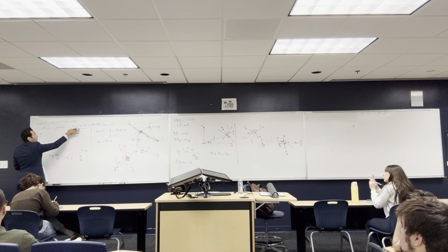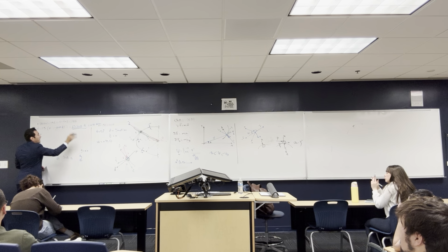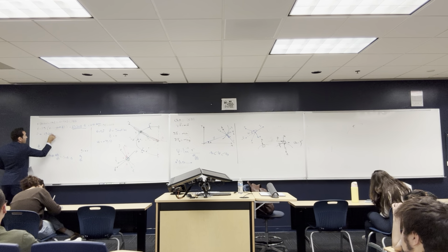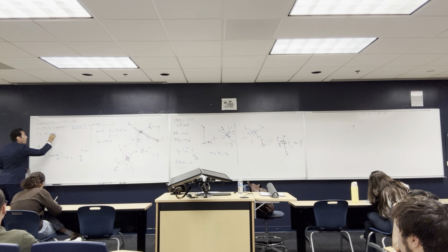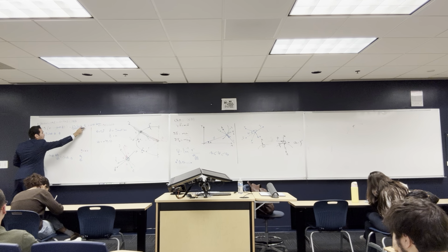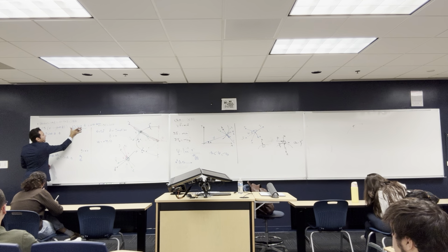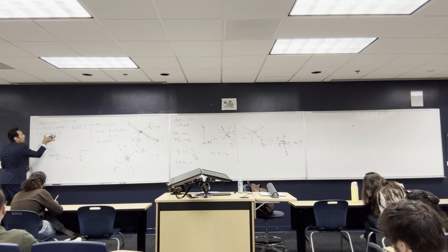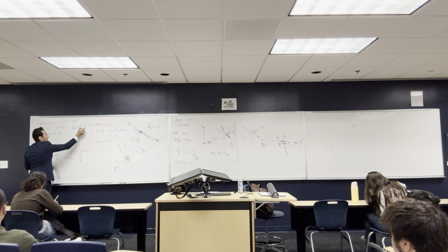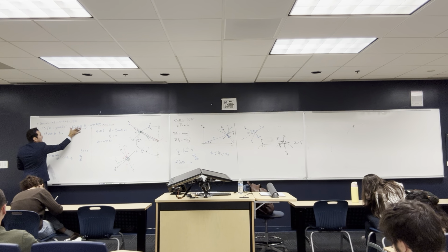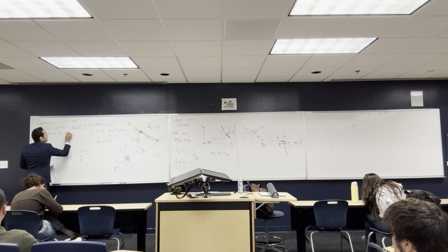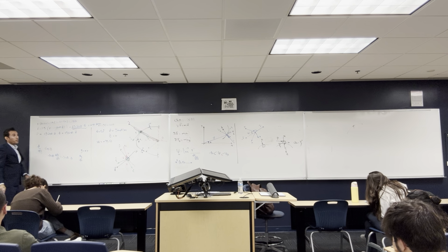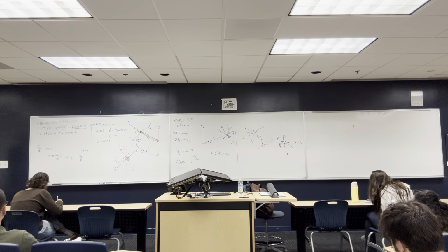So this is going to be the derivative of the first part. I'm going to deal with this one as one function. So this is going to be equal to 1.5 cosine theta multiplied by theta dot. That's the first one. Multiplied by another theta dot. This part is the derivative of this part, 1.5 cosine theta, d theta/dt, multiplied by the theta dot out there, plus the first function, 1.5 sine theta, multiplied by the derivative of this with respect to time, which is going to give you theta double dot, right?